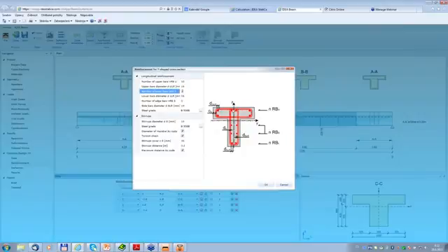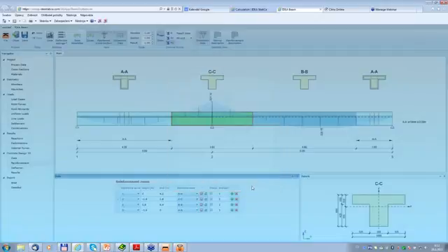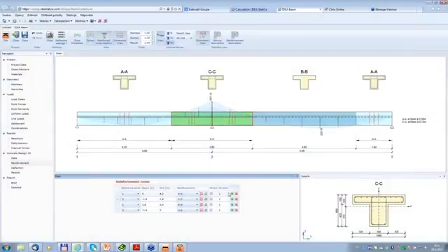That's why I need also compression reinforcement, 3 bars, diameter 16, and I will need 1 bar on both ends, diameter 10. And my stirrups, of course I tested it, were not enough at the distance of 20 centimeters, so I will design stirrups of diameter 10 at a distance of 12.5 centimeters. I hope I defined everything correctly, and I can say this is my reinforcement.